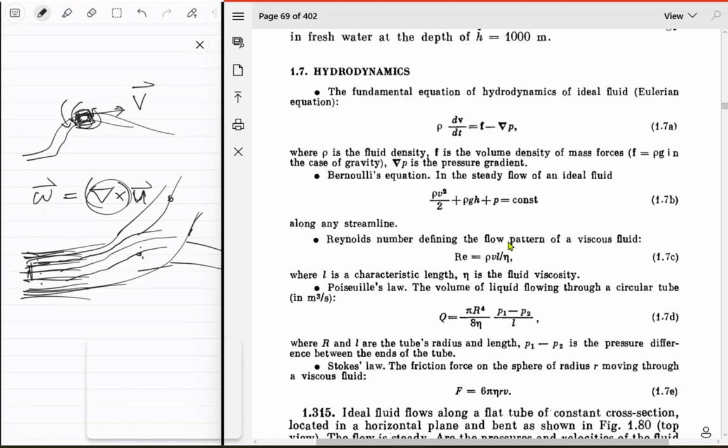That is, if you know where the streamlines start from, which is once again a kind of hard thing to do. But if your tube is thin, just assume there's no difference in the pressures, because our rho gh term will be small. So what that means is that we can just apply this equation everywhere. Yeah, isn't that just awesome, right?